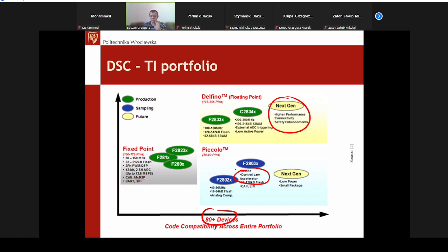Therefore, the lower clocking: in the Piccolo line the clockings are comparable to M3 processors, and in the Delfino line we can count on clocking usually in the range of Cortex M4s, so not super outstanding clock rates, and therefore raw performance not extremely exceptional.